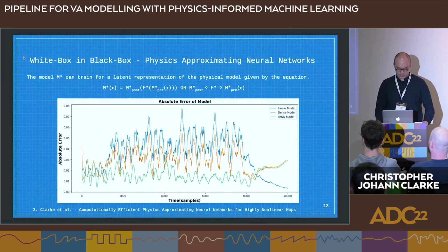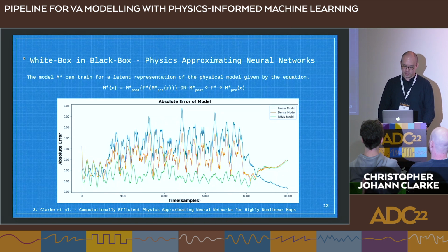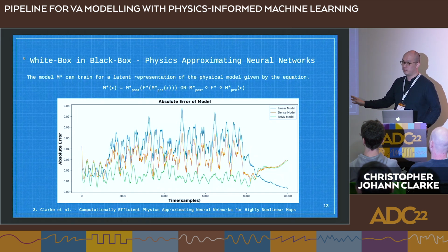This has proven to be a useful method in modeling individual component nonlinearities. The graph here shows the error of 3 different models predicting the output of a film capacitor. The underlying assumption here was that film capacitors inherently add some nonlinearity to the circuit. In green, we see the PAN model provides a lower error compared to the equally sized dense layered model. So the PAN model is 2 by 8 plus the approximation layer, then 5 by 8.